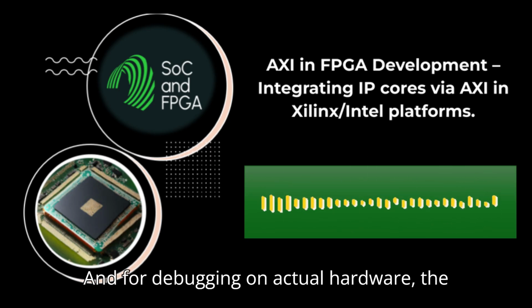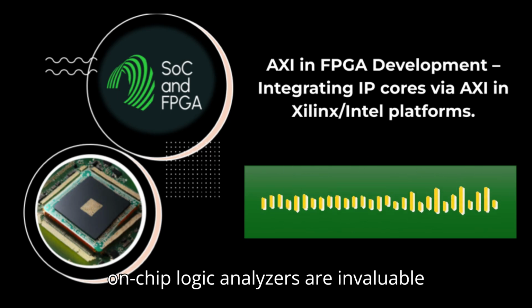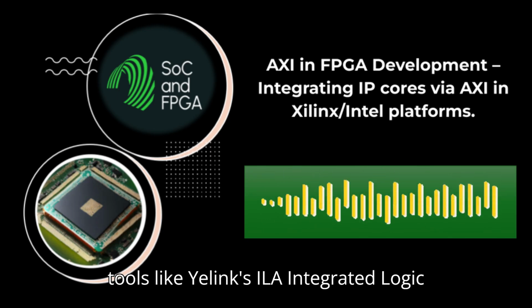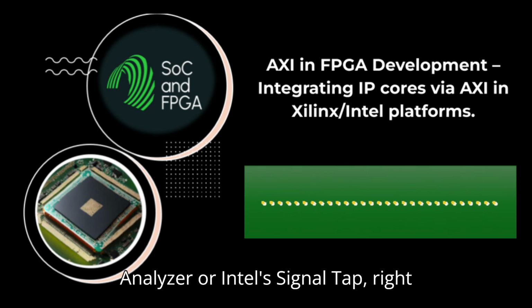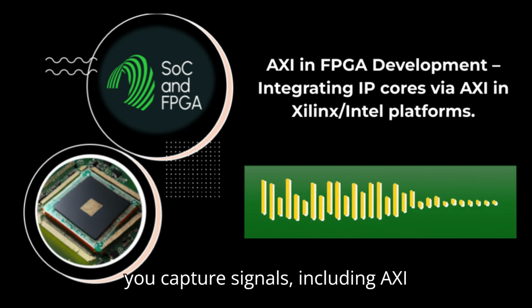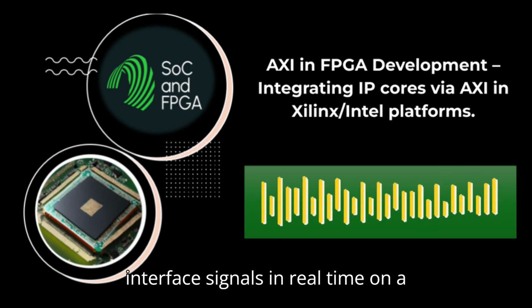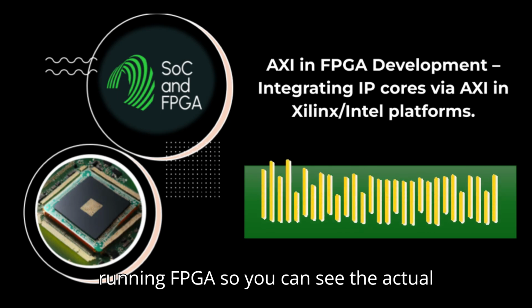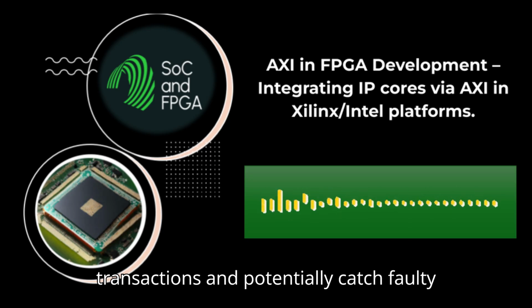Exactly. And for debugging on actual hardware, the on-chip logic analyzers are invaluable. Tools like Xilinx's ILA, Integrated Logic Analyzer, or Intel's Signal Tap. Right, peeking inside the running chip. They let you capture signals, including AXI interface signals, in real time on a running FPGA. So you can see the actual transactions and potentially catch faulty behavior.